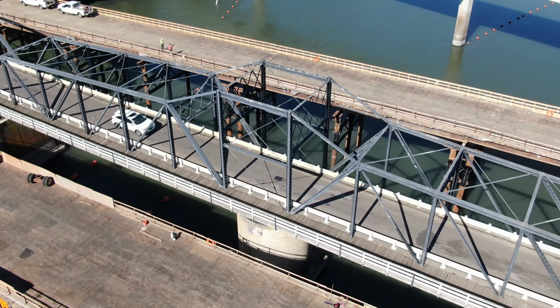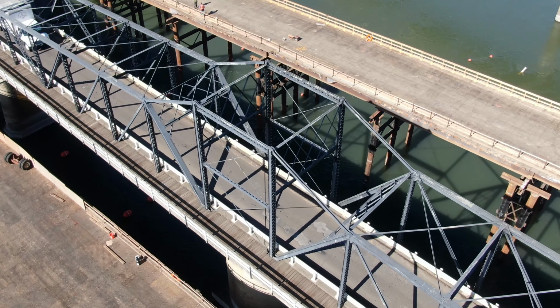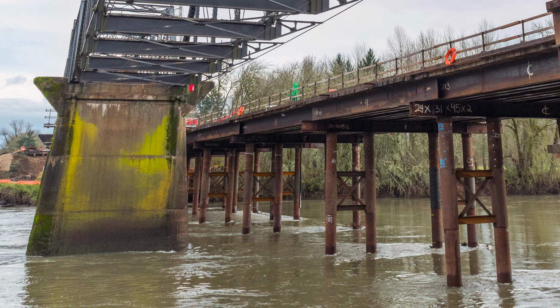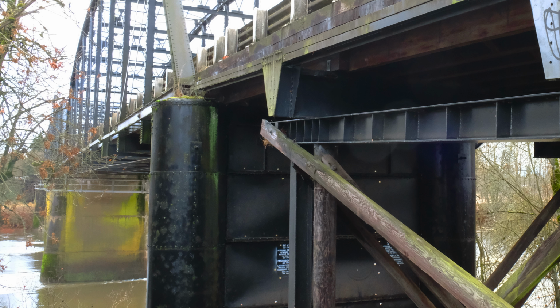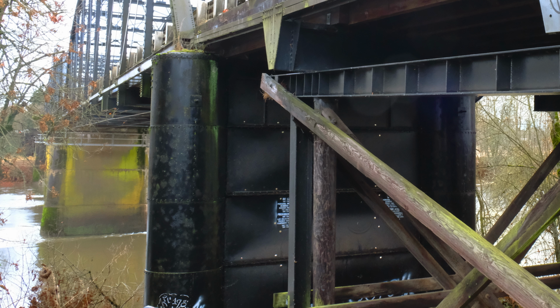Gravity load paths: if you think of a bridge as a set of blocks, the top block transfers loads to the next block, down to the next block. So we'll start with the deck of the bridge, where the cars and trucks drive. That's then transferred into your primary superstructure members, probably steel girders or a truss. It goes down into the bearings and then into the substructure and foundations. Foundations can vary in different ways, with spread footings or piles. So it just goes straight down from the top of the bridge to the bottom of the foundation.